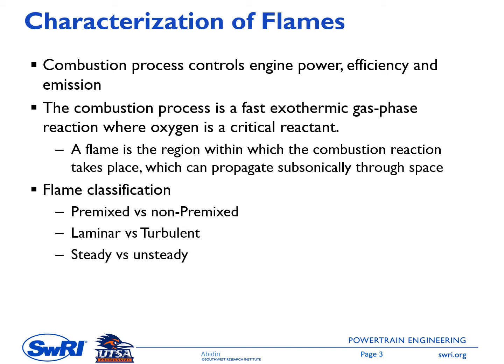Thus, we will see that the fuel-air mixing process plays a controlling role in the diesel combustion process. Therefore, sometimes the diesel combustion process is also called a mixing-controlled combustion process. The combustion process is a vast exothermic gas phase reaction where oxygen is a critical reactant.